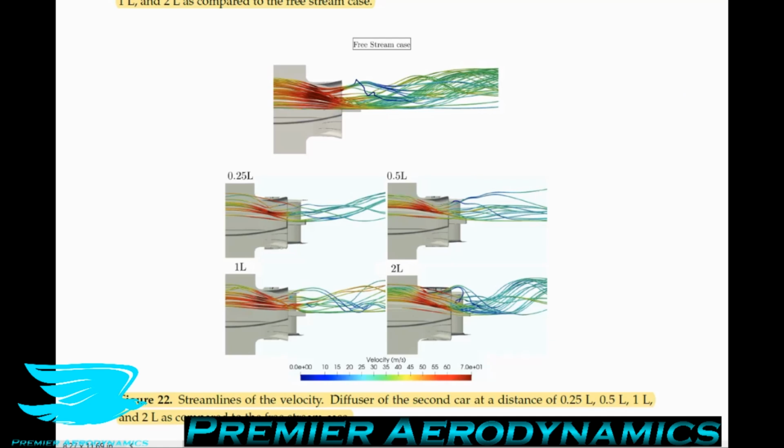What's more, the diffuser is typically curved at the back, and if you have low energy flow, so slow moving flow, there's a chance that the flow won't stay attached nearly as well, and that will result in wakes as well. That results in more back pressure and this bad cycle happening. So I think that not only do we have this low energy flow going through the diffuser, but we also have less flow in general going through, just through continuity. So let's move on from here.